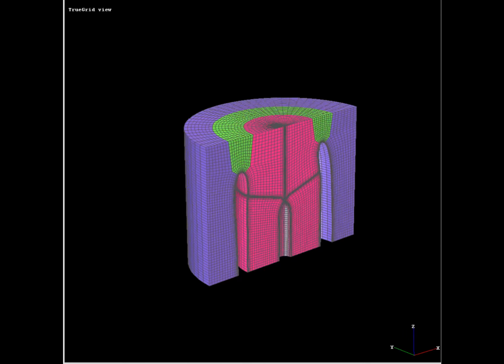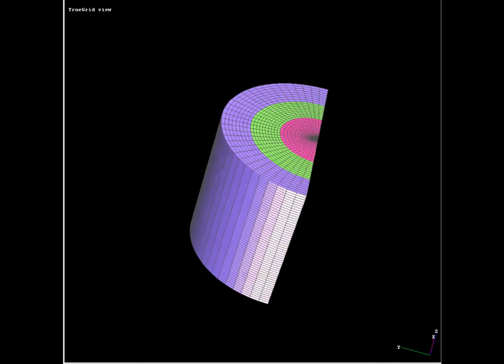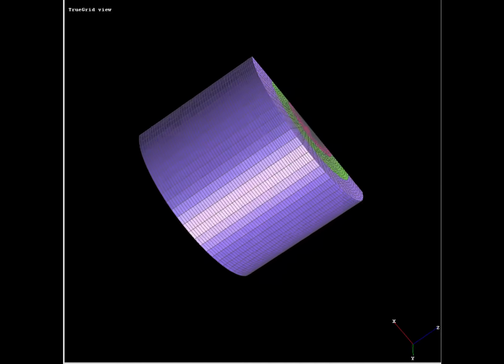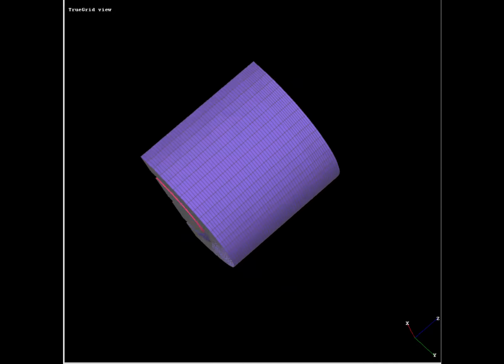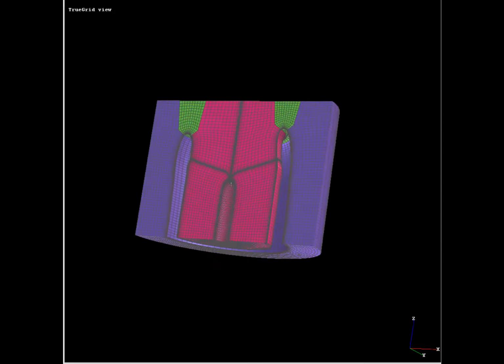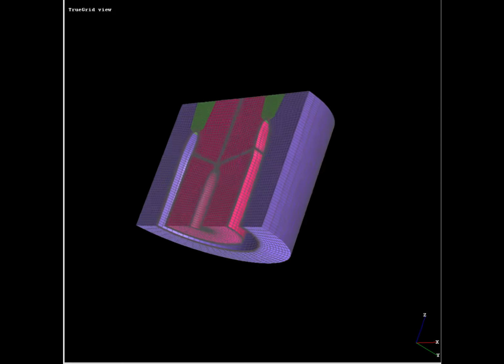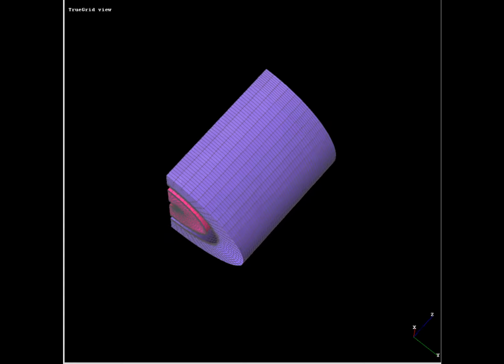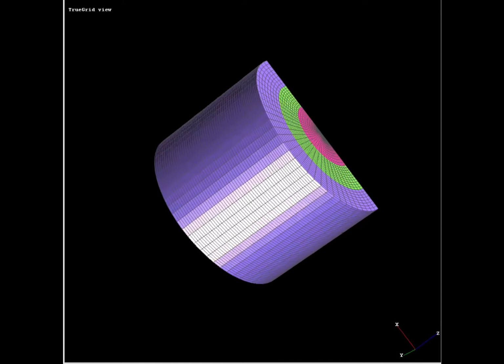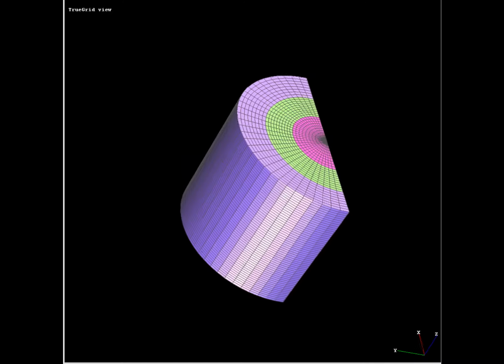The fluid mesh formed by TrueGrid around the nacelle consists of 229,185 nodes and 213,088 hexahedral brick elements. Notice that most of the elements have nearly right angles. Near orthogonality in the mesh is critical to getting an accurate computational fluid dynamics simulation.